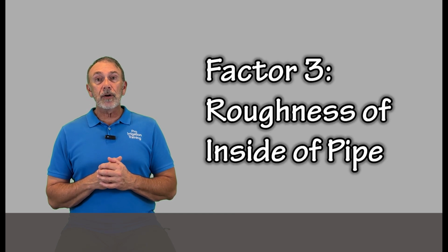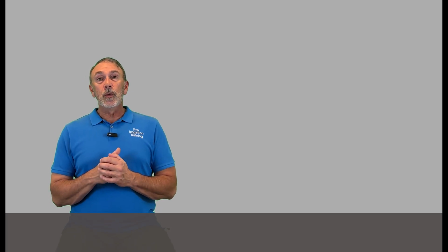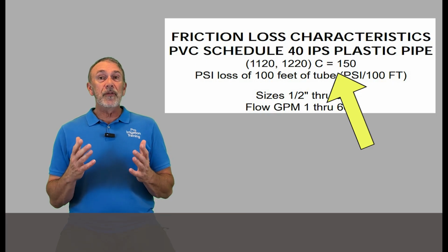The third factor is the roughness of the inside of the pipe type that you're using. And when you look at the friction loss charts, and we'll go over that in the next lesson when we learn how to read a friction loss chart, you're going to see at the top of the chart the C factor for that type of pipe that you're using. And it's different for PVC, polyethylene, copper, steel.